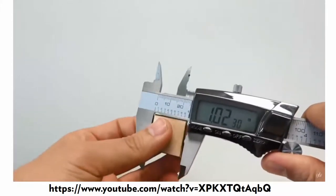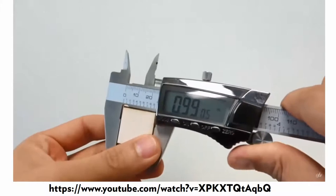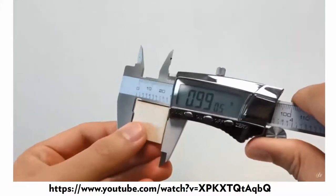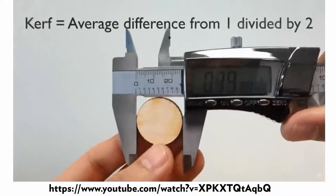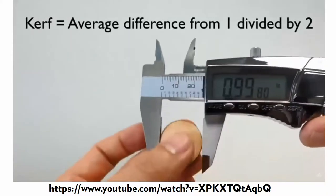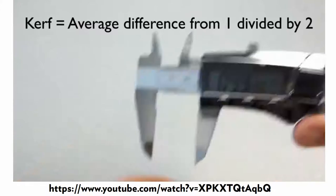When you take down these readings, you want to average them out over how many pieces you have, so 5 pieces. And then you want to subtract that from 1, which is your gold standard, the size that we set within our design software. The difference between 1 inch and your measurements is going to be the laser width. If you divide that by 2, you're going to get your kerf.